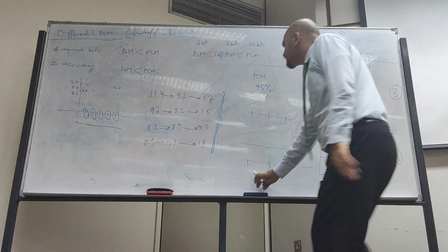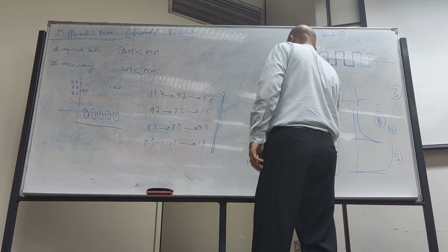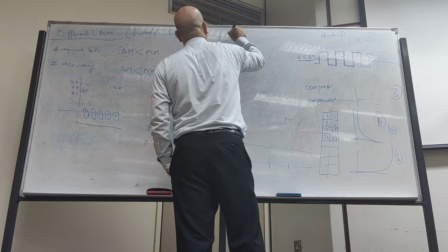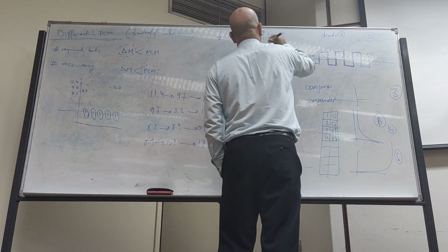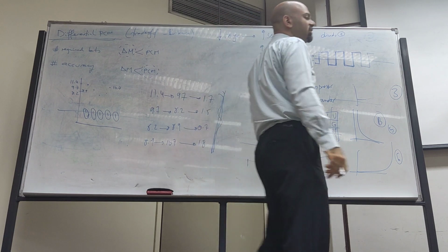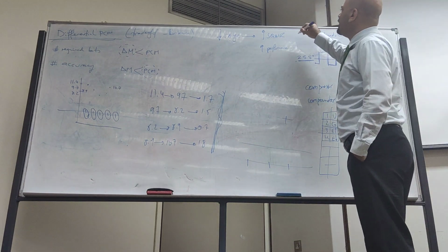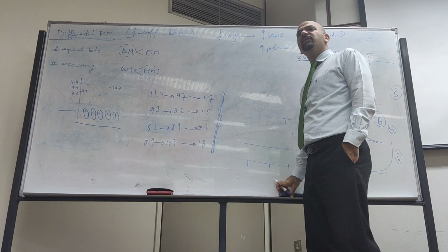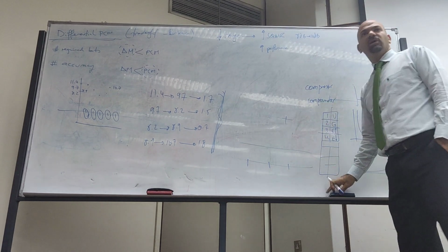Okay, so here with this one, we will have less range. And whenever we have less range, we have better performance in SQNR. And this better performance can be translated into something else. Well, I improved the SQNR from 8 dB to 10 dB. Yes, I improved, but I only need it to be 8 dB. This 2 dB, can I take benefit from it in something else? Yes. How?